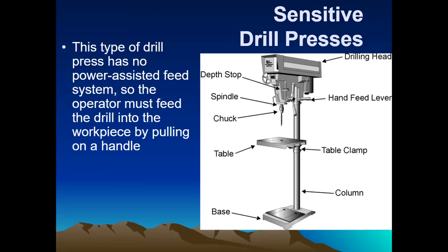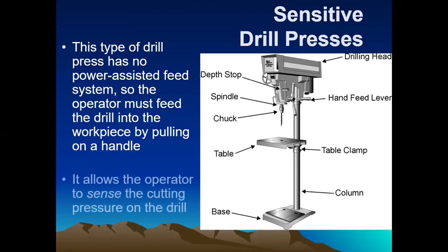It has no power assisted feed. So basically you have to feed it down into the work by hand. That's where you get the feedback. That's why it's called the sensitive drill press. It says it allows you to sense the cutting pressure on the drill.